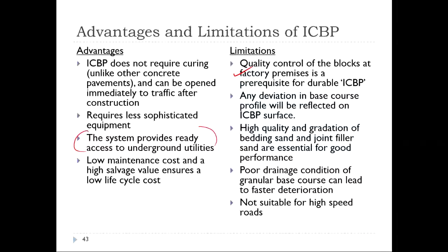Once your jointing sand gets eroded away, there are chances of rotation at these joints. This will cause disturbance in the case of high-speed roads. So this is one of the limitations of interlocking concrete block pavements.